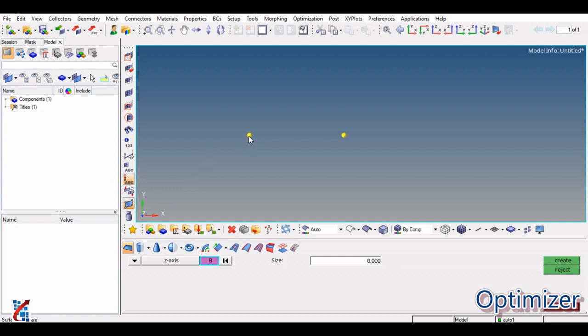Suppose I am going to select the center of the circle as the center of the square like this, and then you can define a size as 100. So I am going to create a 100 by 100 square, and I have selected the center about which the square will be created. Just see, create. So the total length of this one is 100, not this length. Total length is 100 by 100. So this is how you can create a square.